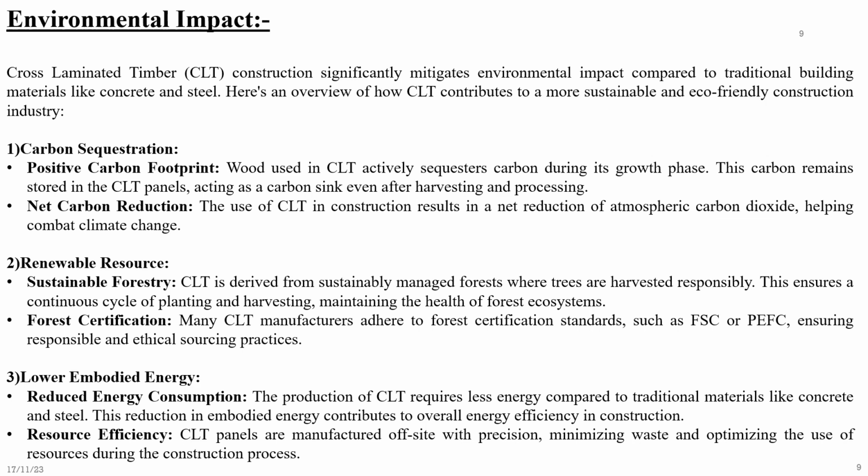Third, lower embodied energy, reducing energy consumption. The production of CLT requires very less energy compared to traditional materials like concrete and steel. This reduction in embodied energy contributes to overall energy efficiency in construction. Resource efficiency. CLT panels are manufactured off-site with precision, minimizing waste and optimizing the use of resources during the construction process.